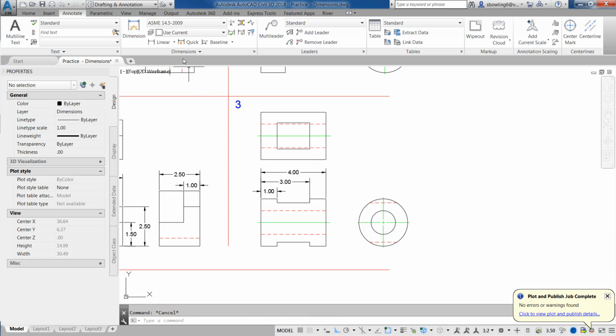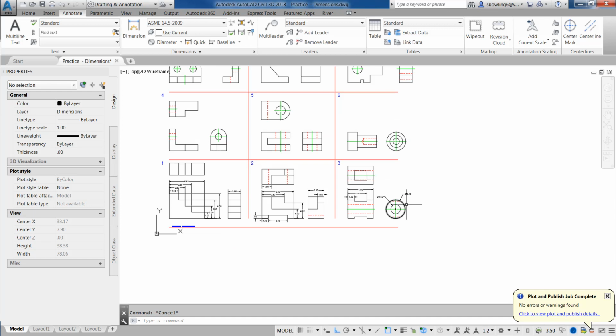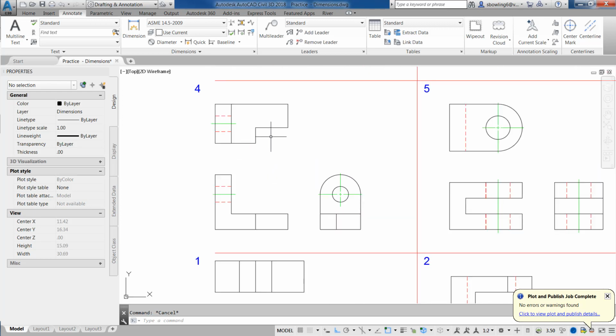Okay, now I'm going to dimension the circles. On the circles, I've got 2 diameters, so I go diameter, and I pick this one, and I just pull it up. Usually they say they want a 60-90, but as long as it's legible for the most part, it's fine. Pick diameter, and pick the diameter, and pull this one up this direction. All right. Now, let's take a look at this one.